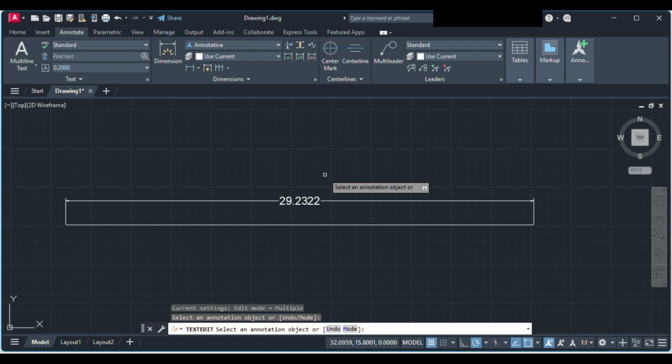Now you can manually change the arrowheads and settings, but in this video we are going to talk about dimension styles, because changing the text size and the arrows separately is very tedious. We are simply going to create a template for our drawing. So a dimension style is like a template for your dimensions. Instead of manually changing, let's say, text size or arrowheads each time, you define a style once and then apply it to all your dimensions. This keeps your drawing consistent and saves time.